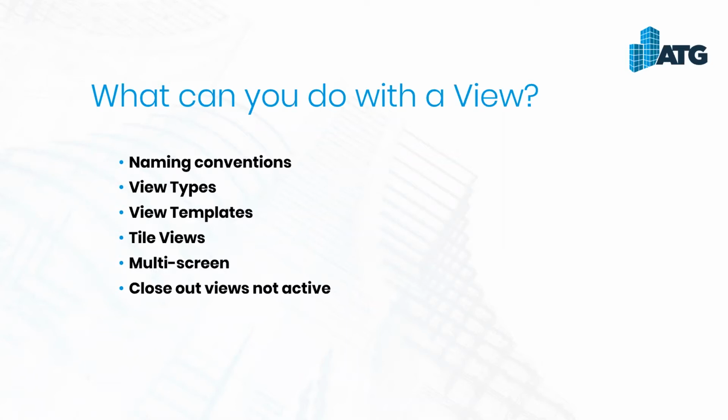The other item is closing out views that are not active. Again, a lot of people will tend to open up views and forget about those, and you just add more and more and more views. Depending upon your computer speed, you might start to see a little bit of a slowdown within Revit if you have too many views. So if you go up to the top in your